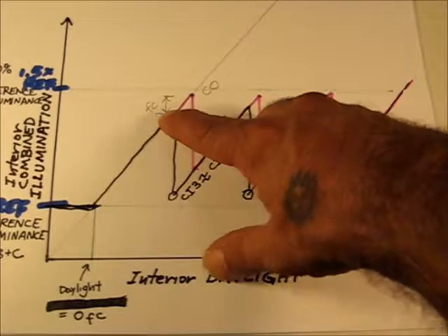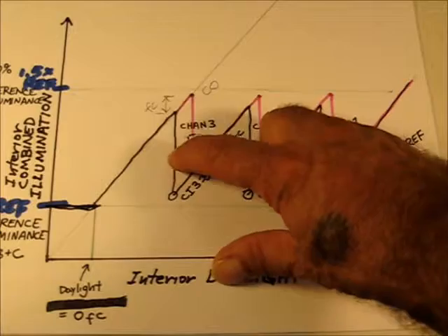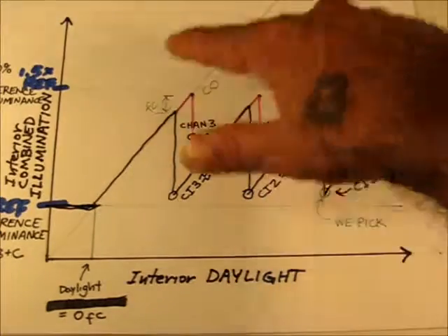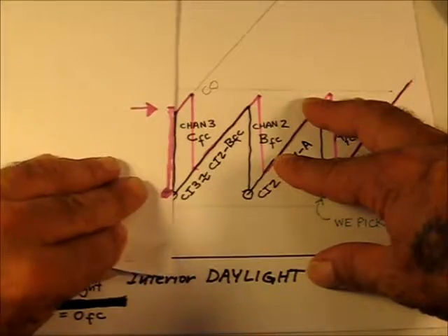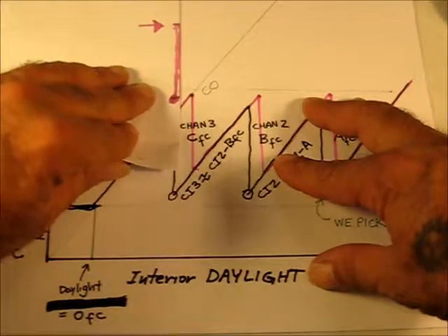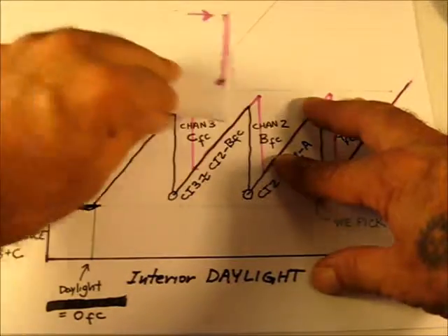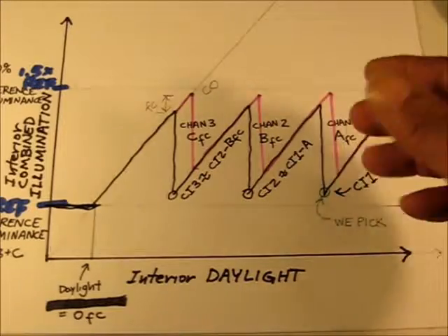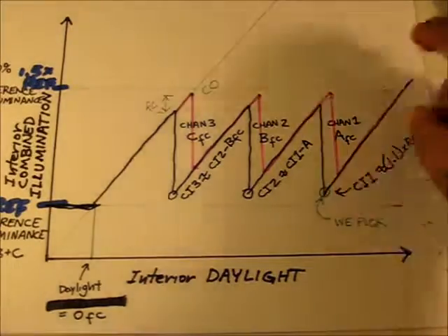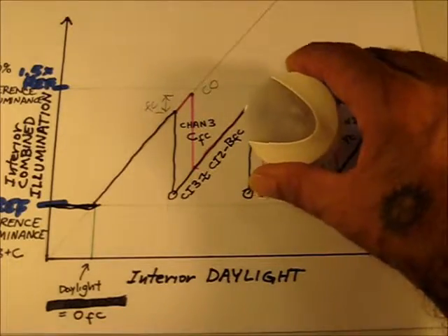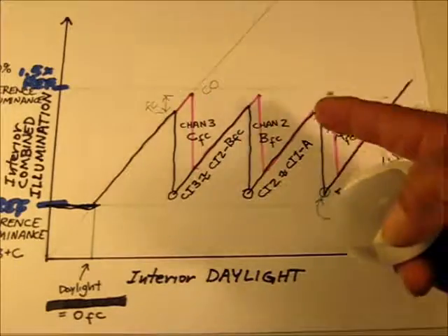This, at a minimum, is the contribution of this lighting stage that is hitting the system sensor. The maximum can be way up there, something like that or that. In the next section, we're going to derive two formulas, one based on the amount of daylight that the sensor sees when a particular channel switches on.